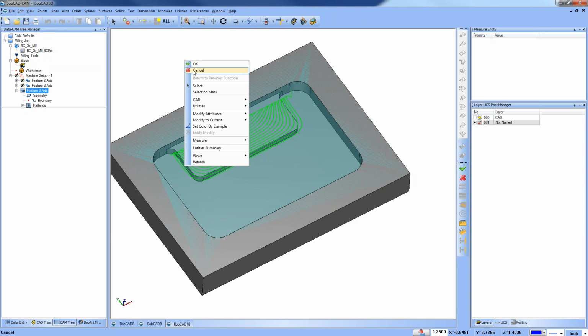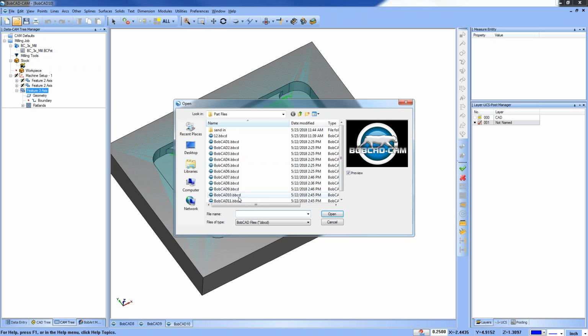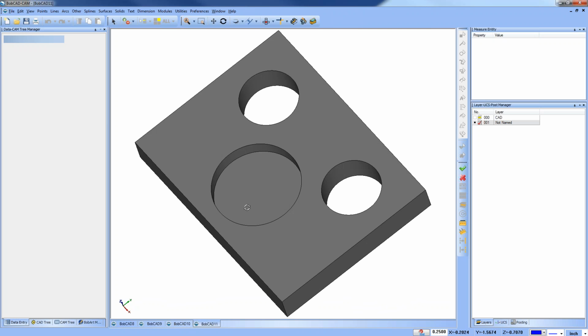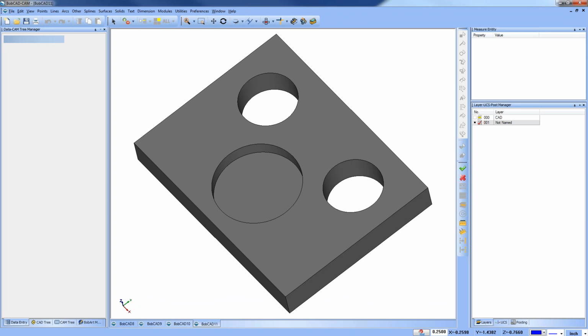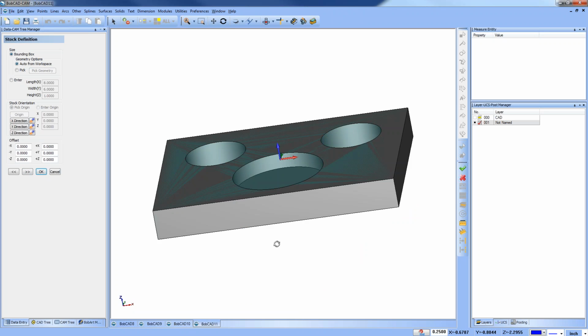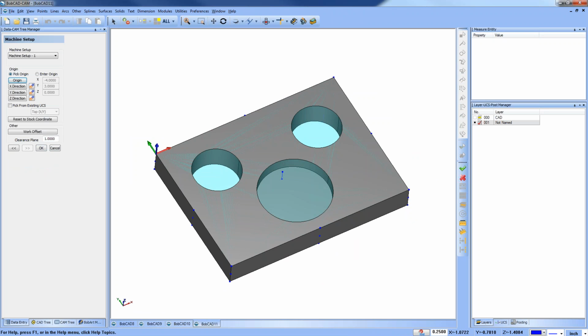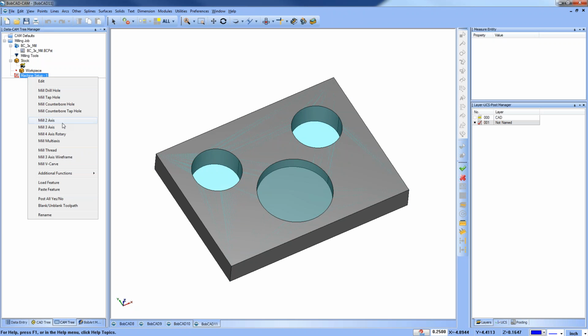Okay, so we're on 10. What else do we have? We have 11 here. Okay, so one of the other things, if you guys are dealing with round circles, whether they're through holes or counter bores, it could be all kinds of scenarios, this is where we would use our spiral pocketing. We're generally going to use spiral pocketing for circular shapes. Again, it could be counter bores, it could be pockets, it could be for your soft jaws. There's all kinds of scenarios.